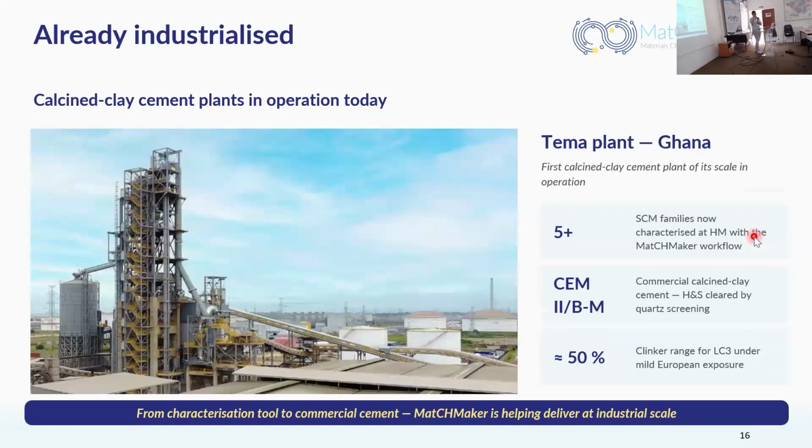Yeah. So for durability, you have standard tests which are not tied to the microstructure, but we know which phases react with the atmosphere. So what we check is how much of each phase we form, and that no strange phase appears which could be an issue with chloride ingress or carbonation. This gives us a first good feeling of what may go wrong with the new cement. And if it passes this check, then we go with the standard durability test.